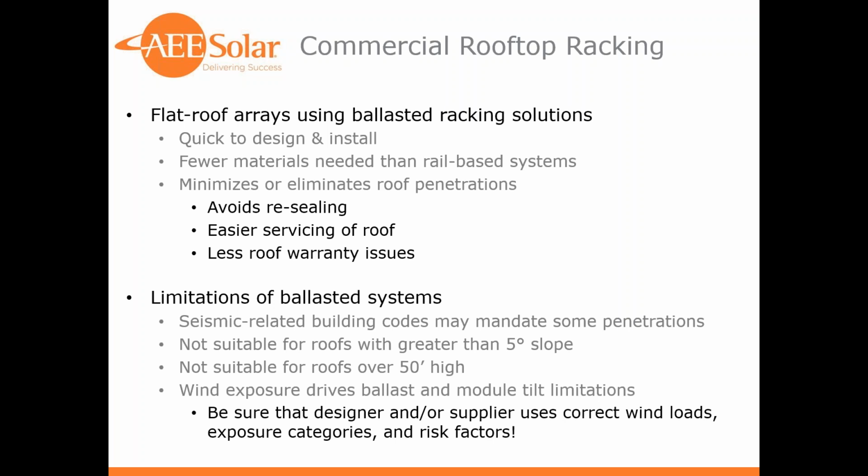Back to limitations of ballasted systems. Once you get above 5 degrees on the slope, the sliding forces tend to dominate more than the uplift. So sliding forces, we've been asked to try to design systems up to 10 degrees. We do occasionally see those get approved, but at times it's just better off going with a penetrating system at that point. Once we get higher and higher roof surfaces, the wind loads tend to pick up quite rapidly. So they're not really suitable for systems and roofs that are over 50 feet high.